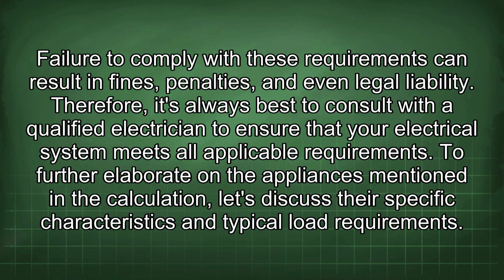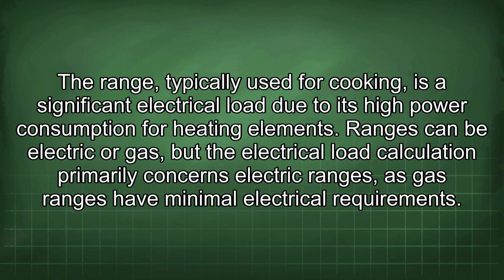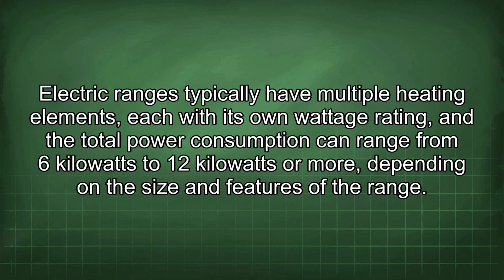To further elaborate on the appliances mentioned in the calculation, let's discuss their specific characteristics and typical load requirements. The range, typically used for cooking, is a significant electrical load due to its high power consumption for heating elements. Ranges can be electric or gas, but the electrical load calculation primarily concerns electric ranges, as gas ranges have minimal electrical requirements. Electric ranges typically have multiple heating elements, each with its own wattage rating, and the total power consumption can range from 6 kilowatts to 12 kilowatts or more, depending on the size and features of the range.